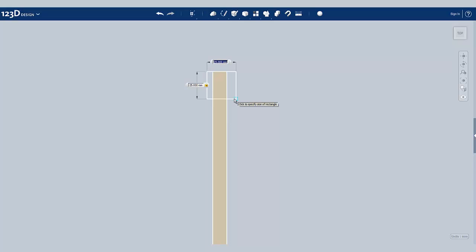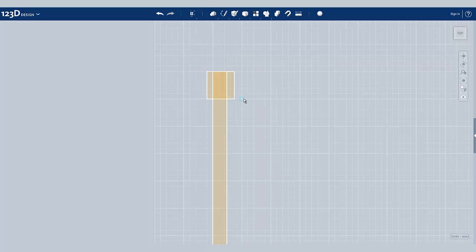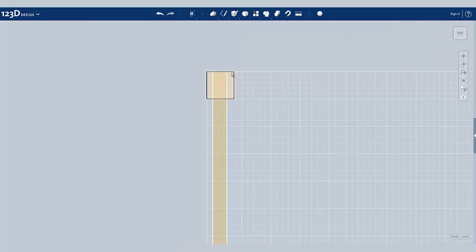One cool trick that I haven't mentioned yet in 123D Design: when you don't have a tool selected, you can select different edges of your sketch and modify them just by clicking and dragging. In this case, I'm going to make our strap a little bit taller than the shield, and I'll make it a little less wide.